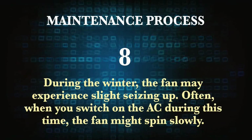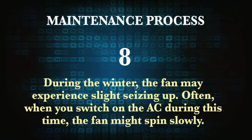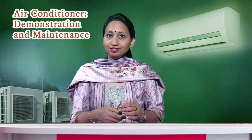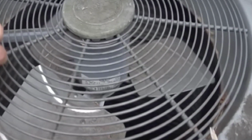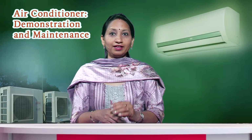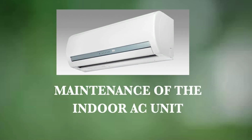Often when you switch on the air conditioner during this time, the fan might spin slowly. You can assist the fan by gently nudging it with a stick or a screwdriver to give it a kick start. If you still have the problem, then either the capacitor is weak or there is something wrong with the motor. Now let us see the maintenance of the indoor AC unit.